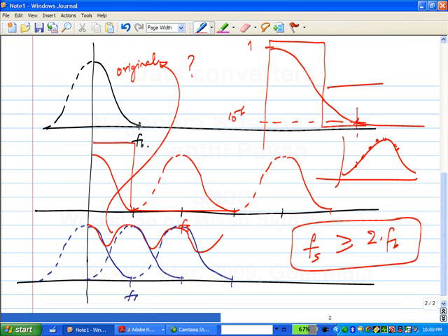I think you always go for uniform quantization. The question is how much error you will make, and that you have to limit. And like somebody pointed out, it depends on the situation. But if the rounding is 1 rupee, the error is 50 paise. That is very clear, right? Similarly, if the rounding is some VLSB volts, the maximum error we will make will be VLSB by 2. We will see what the effect of that is soon.